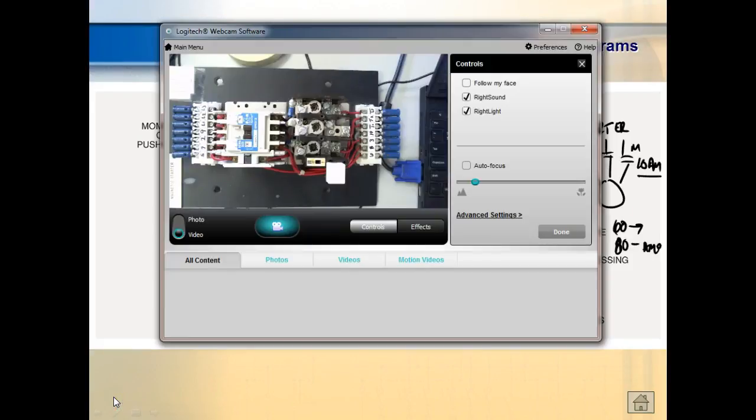This is what we call a motor starter. And a motor starter is designed to run what? Motors that don't have internal overloads. Now, a lot of your single-phase motors have overloads built in them. Sometimes they'll have a little red button on them that you can push. Sometimes they auto reset. So that means if you overload them, the little thermal overload will kick out, and after it cools back down, it's going to take off again, especially in all your HVAC systems, guys. So be real careful there, because that can eat you up.